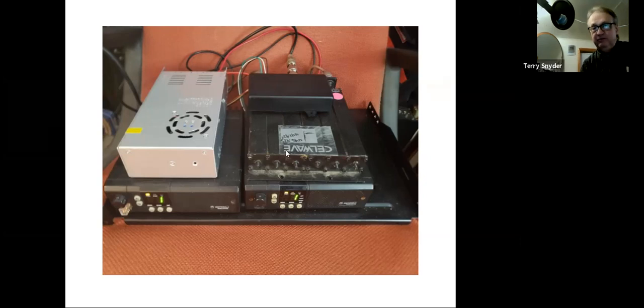Being a 440 megahertz radio, check out the size of that duplexer. That one you can fit in your hand. If I stretch my hand out, I can put it over top of that. That's how little it is. This has 6 cavities in it. They're smaller cavities, but that's a mobile cable wave, Celwave actually makes this one. I have one for a 440 repeater that's in the works. And on top of that is a box that houses a controller.